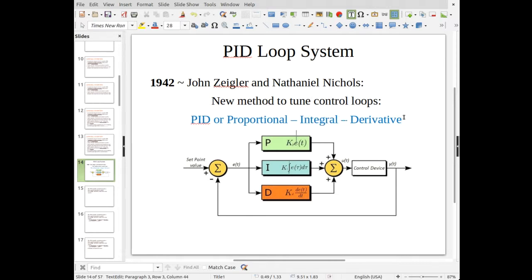Now the proportional piece happens every scan. All the proportional piece does is multiply this gain times the error every scan. That can happen every single scan, and then make an adjustment to go out.